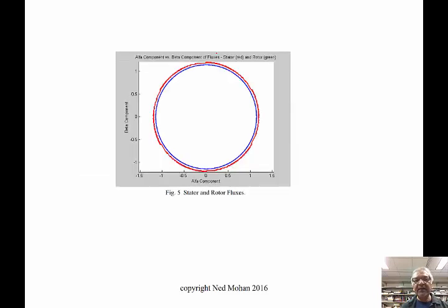And you can see that both rotor and stator flux linkage space vectors, the amplitude is pretty much constant, and maybe a slight jitter because of the thickness of the hysteresis band, and here the position is plotted in XY coordinates, alpha and beta coordinates here.